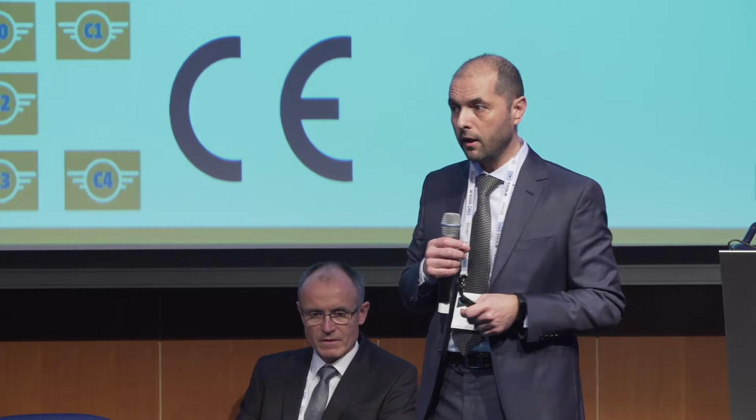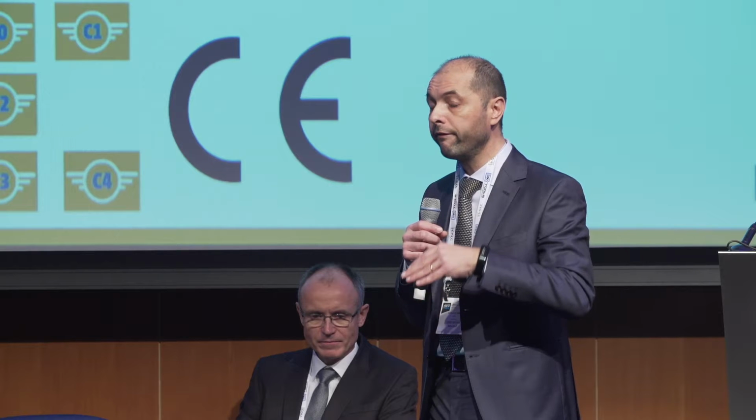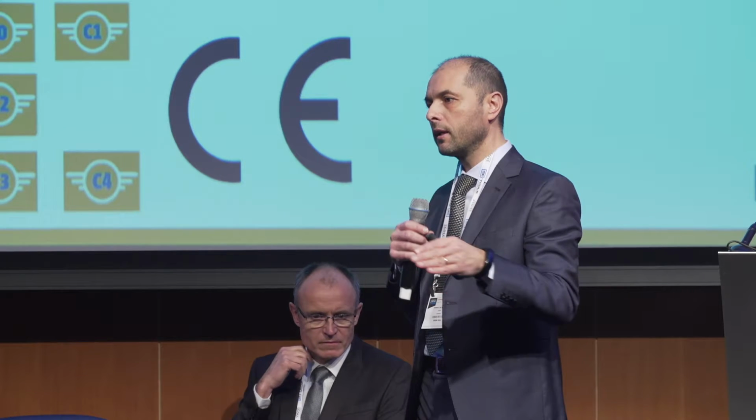If instead you want to do something more, so maybe you want to have a drone that is a little bit more heavy than 900 grams, you can buy a C2 drone that is up to 4 kilos. And in this case, you can fly close to people. This means that you can fly up to 5 meters to people, so not directly over people, but up to 5 meters, or 30 meters, depends if on board you have a low speed mode.